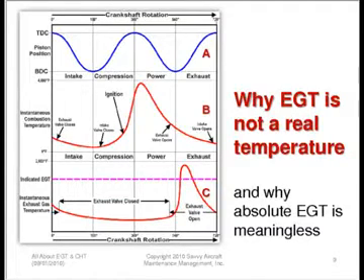And you'll notice there's actually a period of time from here to here where both valves are open. It's called the valve overlap period. It's a fairly short period of time when the intake valve has started opening and the exhaust valve hasn't closed yet. At any rate, that's what we would see if we were able to put a temperature probe inside the combustion chamber. But, of course, we don't have temperature probes inside the combustion chamber.